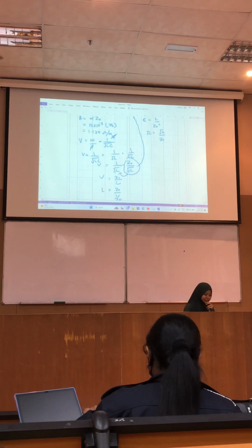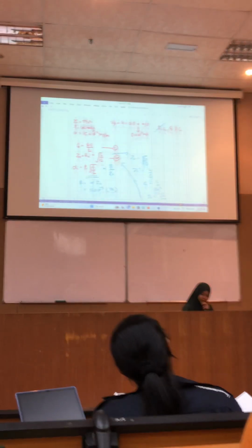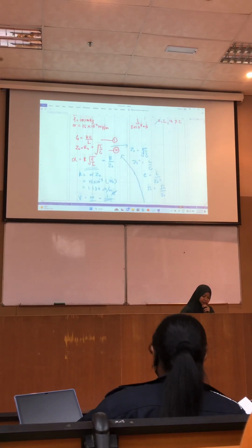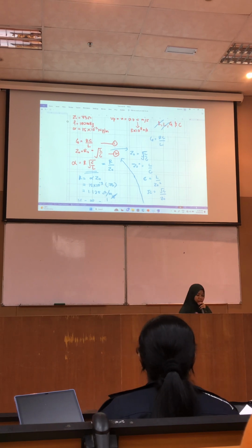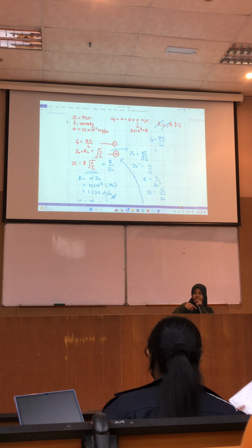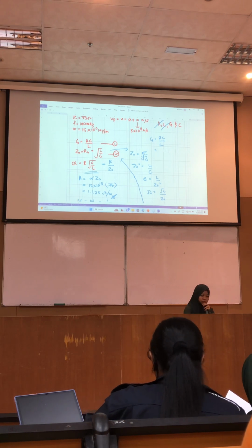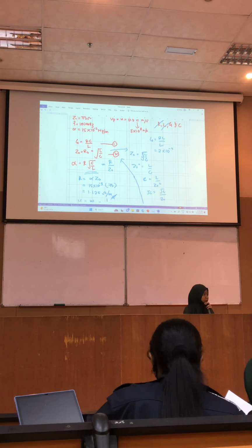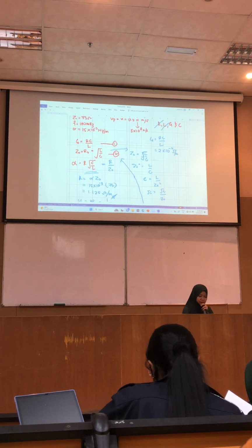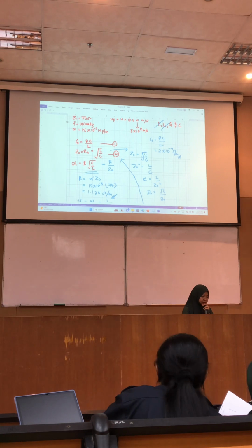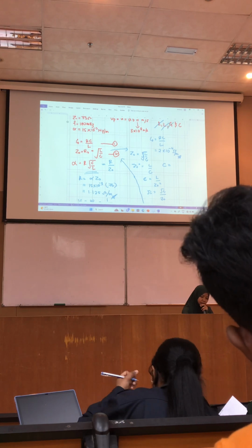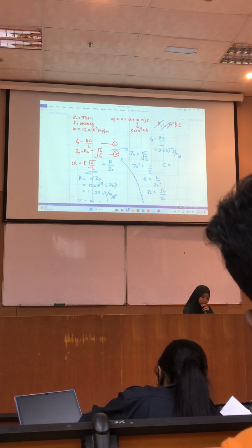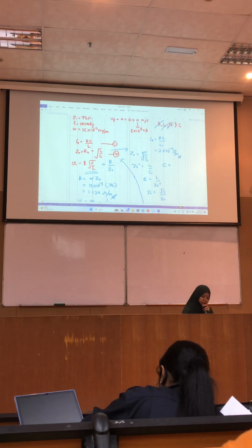Okay, next. R, G. Okay, the interlude is over. L, okay, L is done. Okay, G is equal to RC over L. So R, C and L are all known. Just substitute the value and you will get 2 times 10 to the power of minus 4 Siemens per meter. And last is basically C. We should find C first.